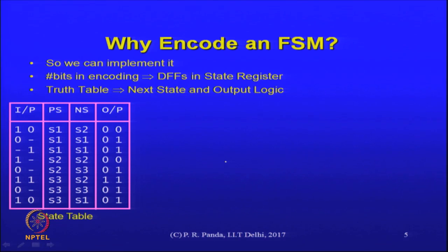First question is, how many bits should I have in that encoding? That bit there is relevant because we know the standard template, right, how that logic looks like, the hardware that would implement a particular FSM. Every bit in the state encoding translates to what? Or a longer or a shorter encoding length has what implication on the hardware that is inferred?